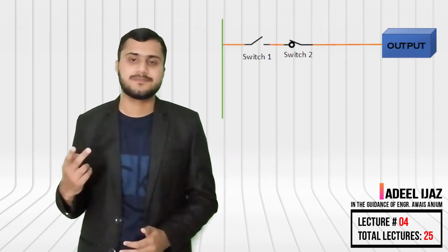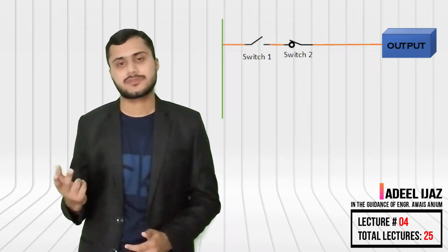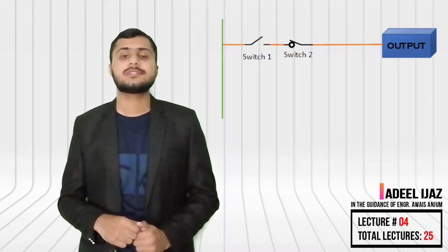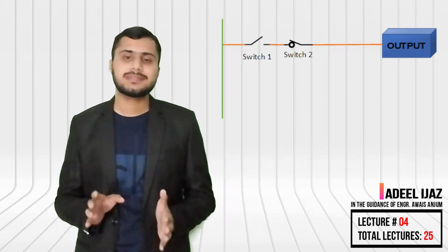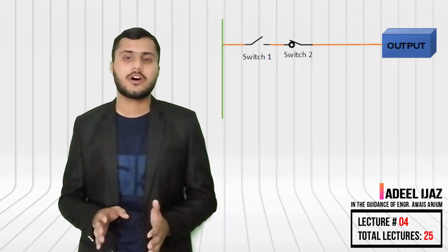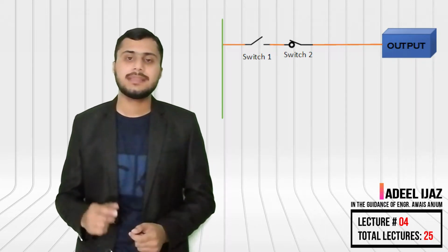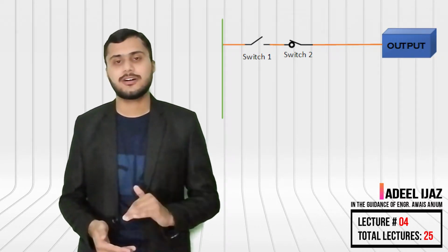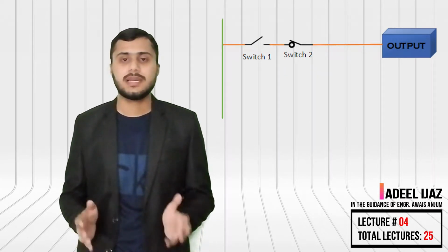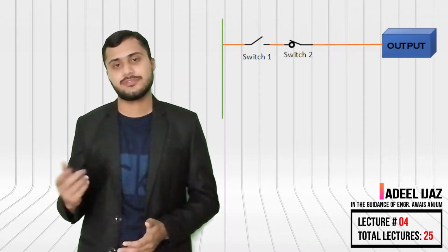In our first example, we are going to make a simple program with the combination of LD, LDI and OUT instruction. In this program, we have two switches which are X0 and X1 along with one output which is denoted by Y0. Now what this program does is that if we press the X0 switch to on, then our output Y0 will turn on, and in that on state, if we turn X1 on, then our output Y0 will turn off. In all other cases, Y0 will remain off.